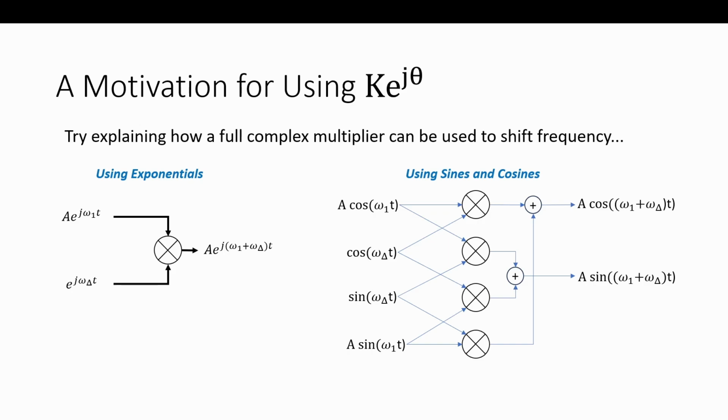And then, of course, when you're detailing all this in the single sideband modulator and getting down to implementation, you can then ask, hey, is that single frequency, or the modulated waveform, high enough that I can take the real part, which creates the negative image, and now it's back to a cosine, and it pops up. They don't overlap, so you're safe to do it. If they overlap, you can't, and that's why we need complex I and Q, if that matters. So then we go to implement this thing, and yes, a full complex multiplier requires 4 real multipliers and 2 adders, but I'm not thinking that way to understand it, process it, or even explain it, right? It's much easier.